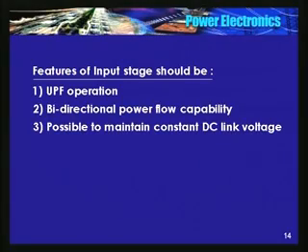Can we address these limitations? So if I summarize, the features of the input stage should be unity power factor operation, bidirectional power flow capability, and possible to maintain constant DC link voltage. So these are the features the input stage should have. How will you achieve it?